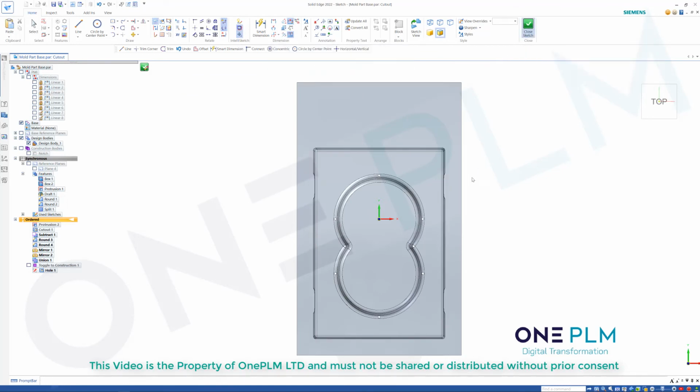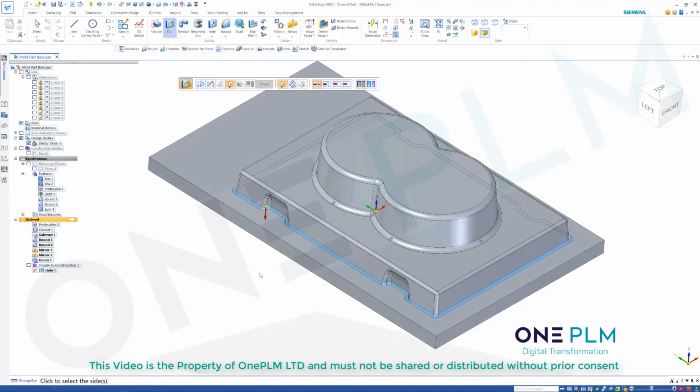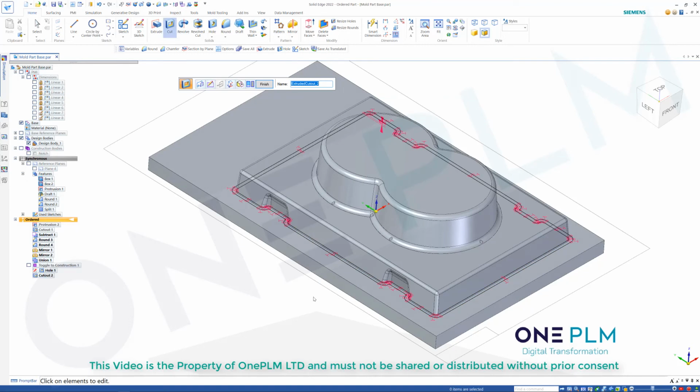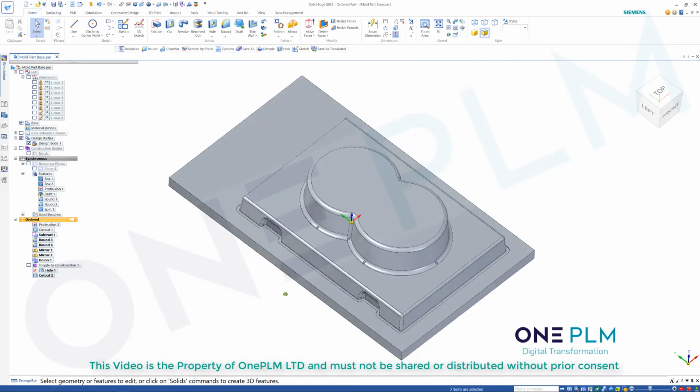So we close our sketch on that. This time it's obviously going all the way through next, so we want to make sure we're on single-sided extent, or that both those options are off if you're on an older than 2022 version. So click both off, or for 2023, even 2022, this version. And then for here, we're going to do extent. I'm just going to go down 1mm on there, then left click to confirm, and right click to finish. That sketch should disappear for us now.